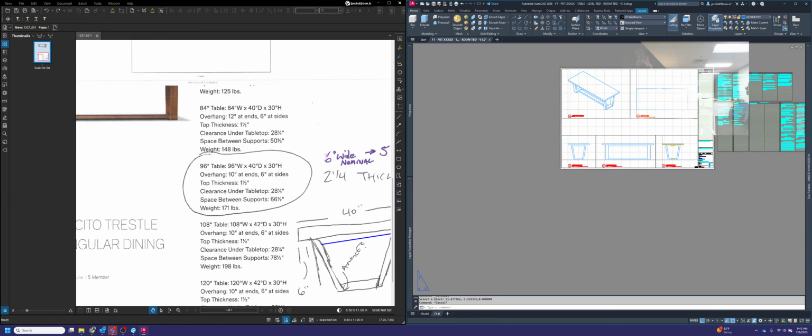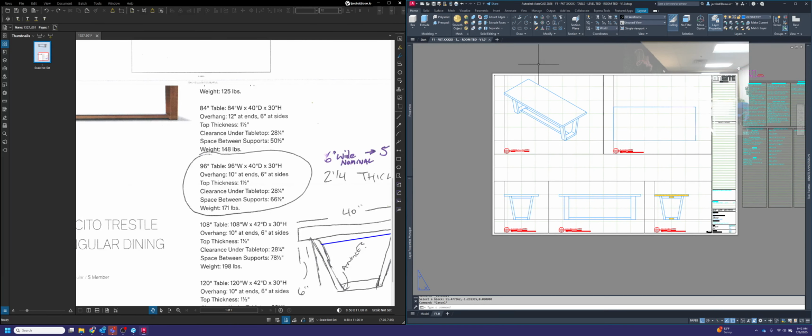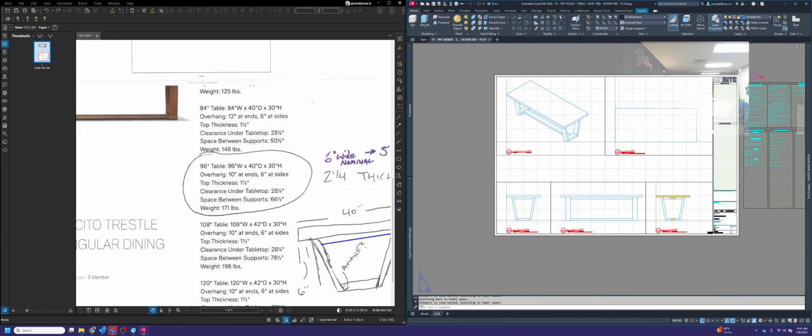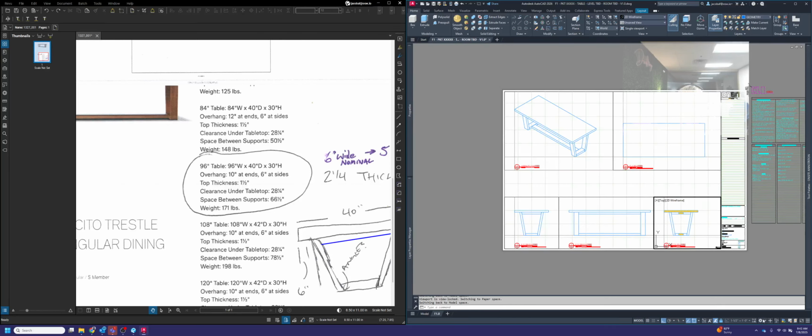All right, so last thing before we start dimensioning and tagging, let's make sure that all of our viewports are locked and at an actual legitimate scale and not some weird decimal. You'll see your scale factor right here next to the lock. Make sure that is set to what you want it to be and not something goofy. If it's set to something goofy, odds are you may have had it unlocked and you might have zoomed in a little bit and it will affect the scale here. So be careful not to do that.